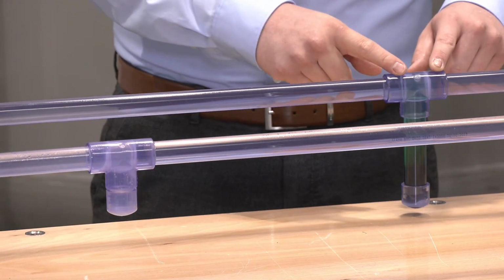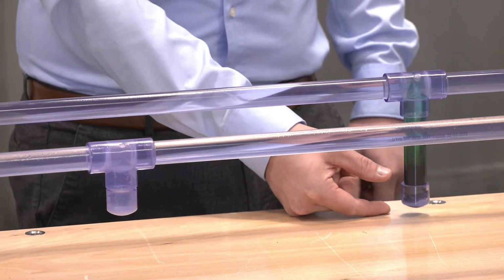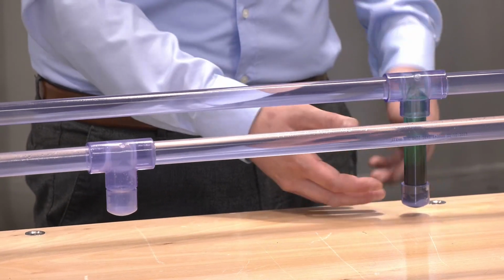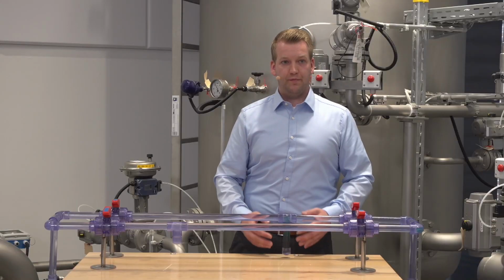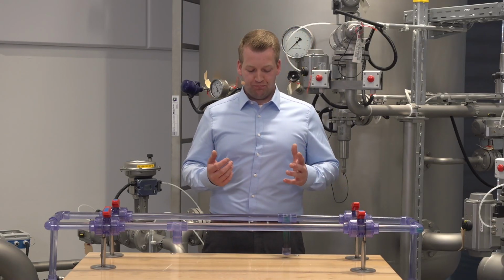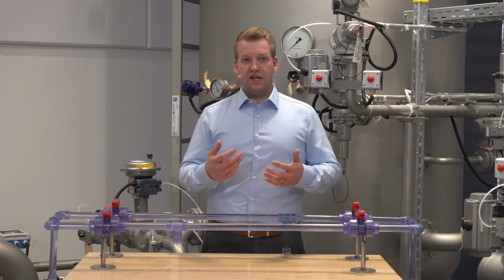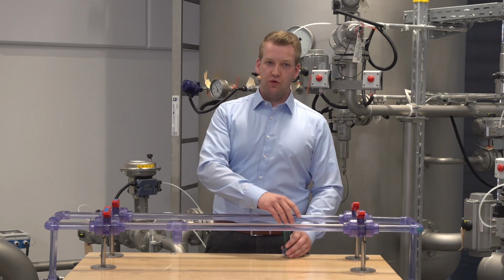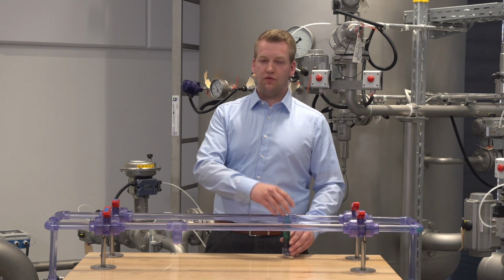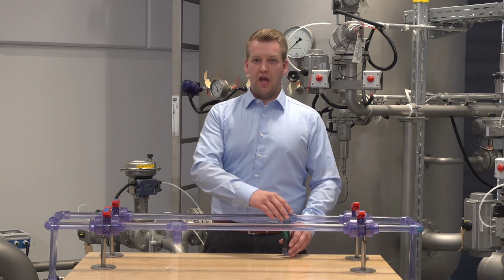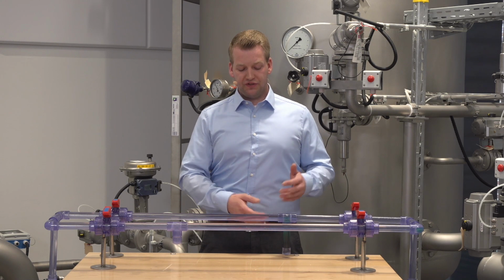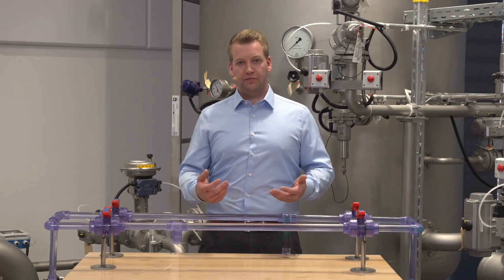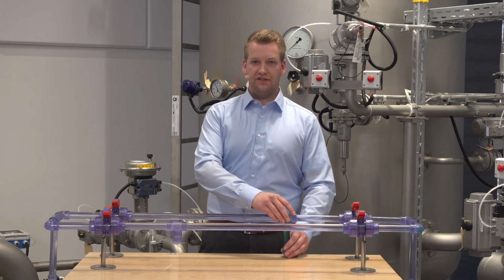If we compare it with the color here, we see in the lower area the dead leg. And the dead leg, as I told you before, is an effect where we need additional effort to clean the safety valve. We must remove this safety valve, for example, and there is no automatic process behind it, so this is typical of cleaning out of place. So remove it and clean this safety valve here.